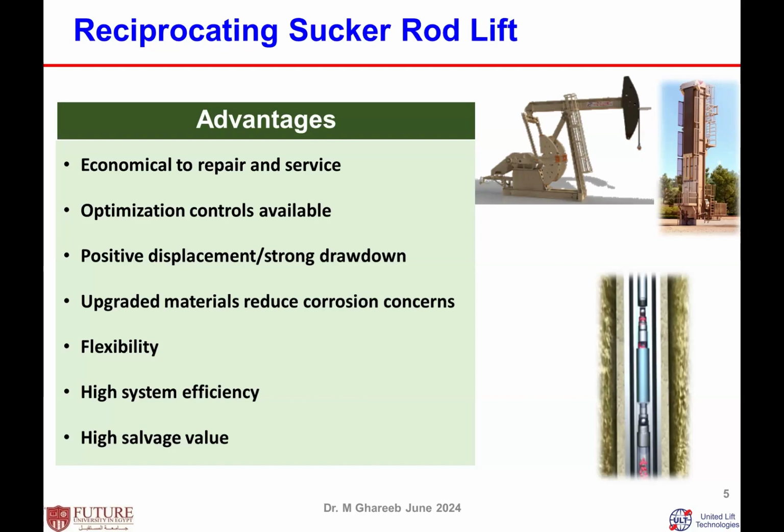Well conditions such as pressure, fluids, the amount of gas increasing or decreasing, sand, and so on. It is very flexible to adapt this technology. And you can even change the pumping parameters from the surface to match the well productivity downhole. One of the good things about this is high system efficiency. I mentioned that before. System efficiency is how much power I gain compared to how much power is used to run this system, how much horsepower I give to the system.